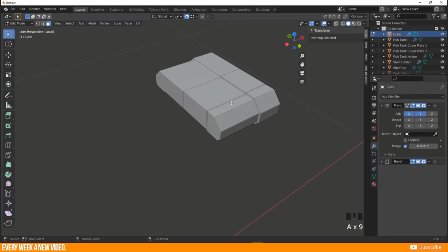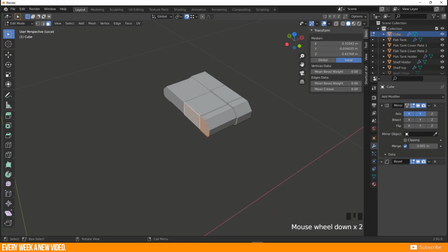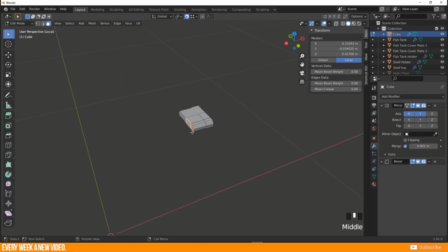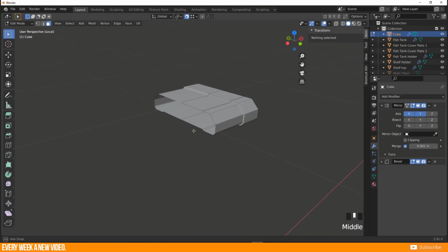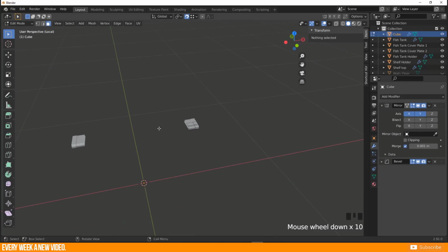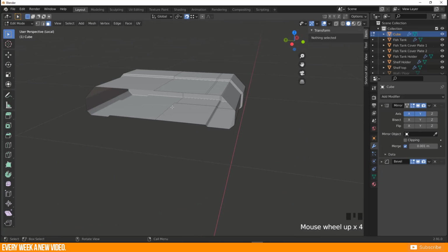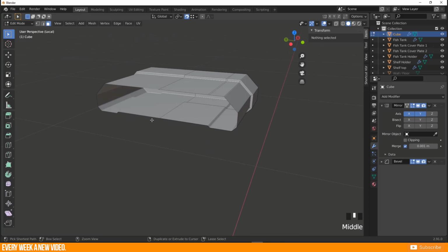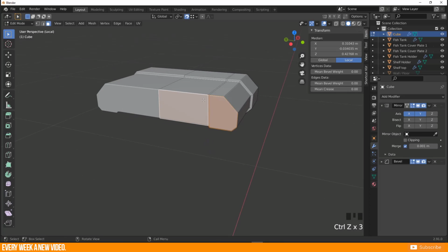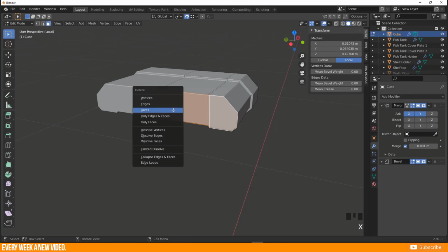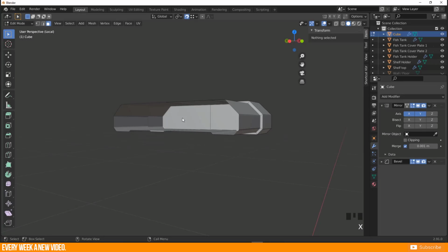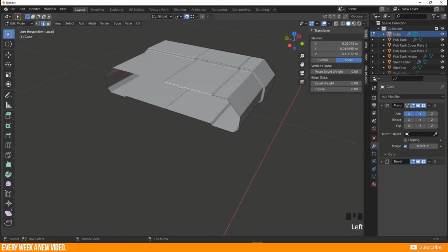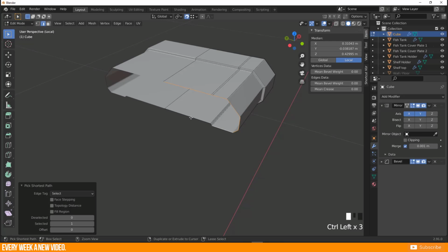So now everything is deselected, and I can again select those faces here and remove them, because in the end there will be a merge here in the middle, and there shouldn't be those faces. When you extrude, all these faces will be created, and we don't need this face and this face here as well. This is unnecessary too. I only need this outer ring here.